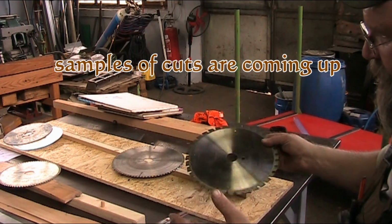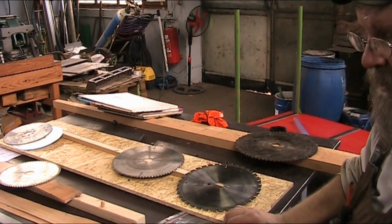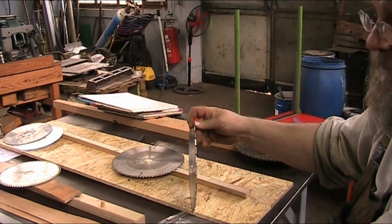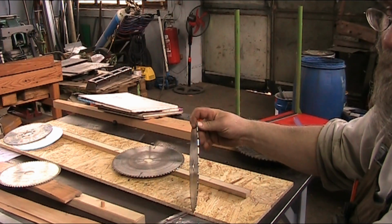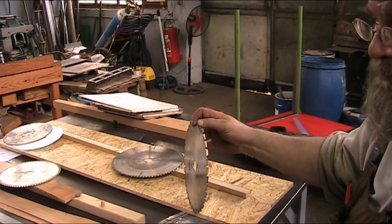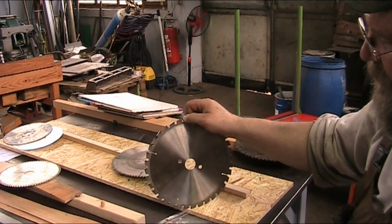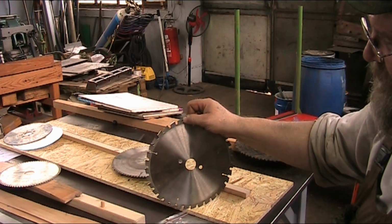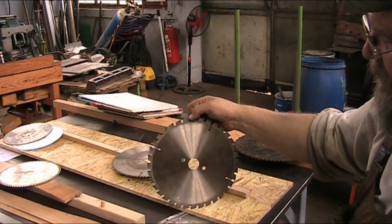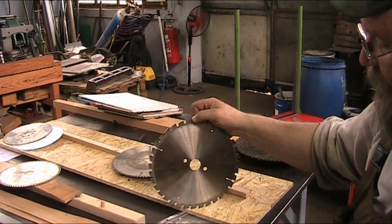Now, this is a carbide tipped blade, and so some of you folks out there who like the carbides, just be aware that you don't have any side clearance on the side of the teeth, and as your blade dulls, you're creating much more pressure on your wood fiber, and it pushes away, and then as the blade comes past, the back of the cutting edge of the tooth passes through the wood, that fiber expands again and then rubs up against the side of the tooth, and that's what's creating the burn in your cut.